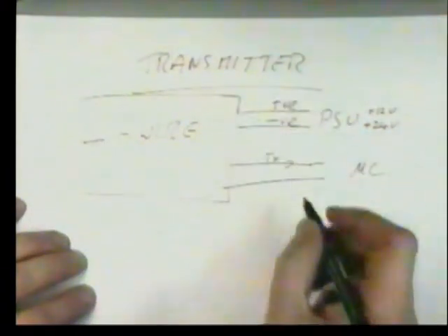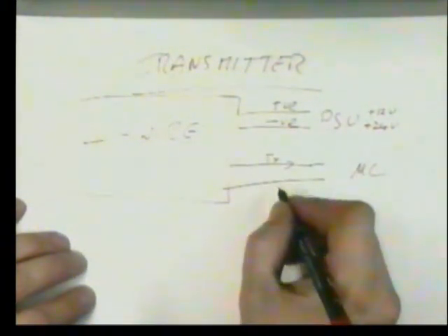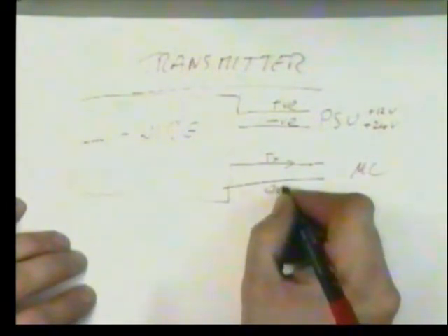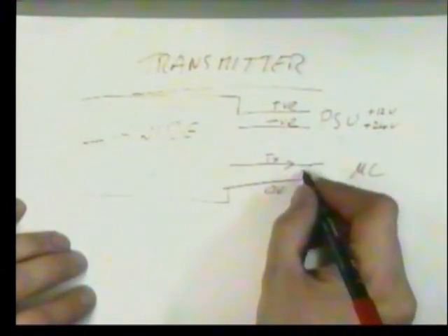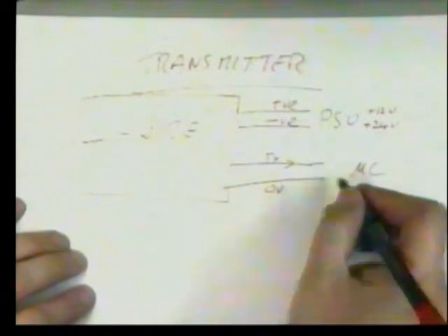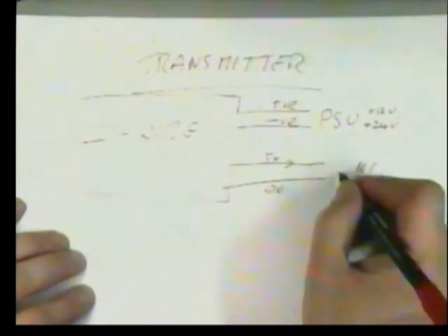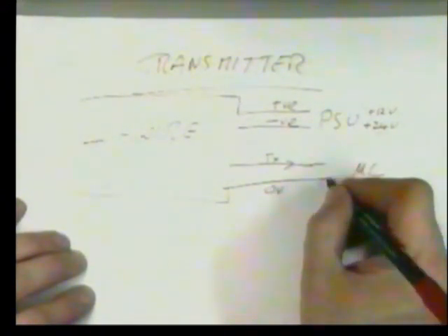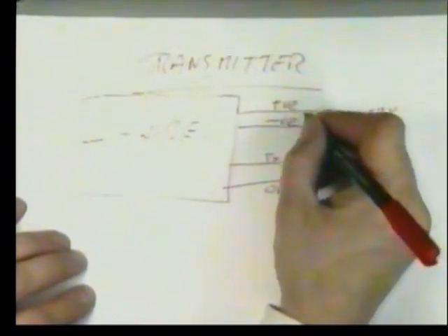Here is the 4-wire transmitter, our 4 wires. The other signal is a 0-volt reference that the transmitted data is referenced to, so that we have the ability to have an independent transmission loop, totally independent of the power supply. Now that's done for very noisy environments.